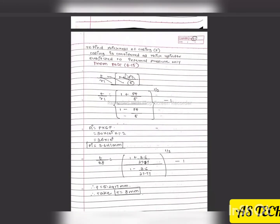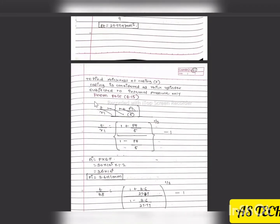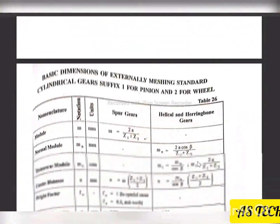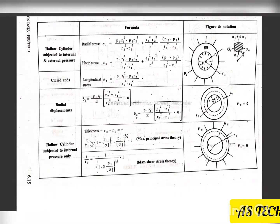Now to find the thickness of casing, the formula is given in PSG at 6.15. So for the thickness of casing, this formula we have to use. T upon R1 equals, in bracket, 1 plus P1 upon sigma divided by 1 minus P1 upon sigma, raised to 1 by 2, minus 1.